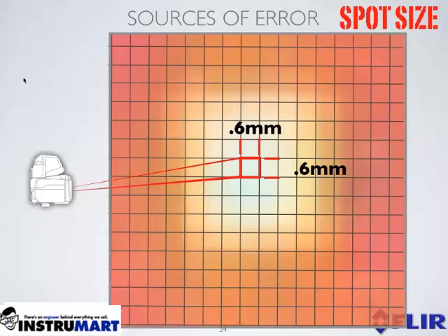This slide shows a zoomed-in view of our 2.5 millimeter target. This is my tape target as it appears in infrared. And as you can see, at a distance of 0.2 meters, our camera lens combination results in about 64 camera detector elements sampling our target. I have more than enough pixels available to sample my target and make a measurement with the infrared camera.